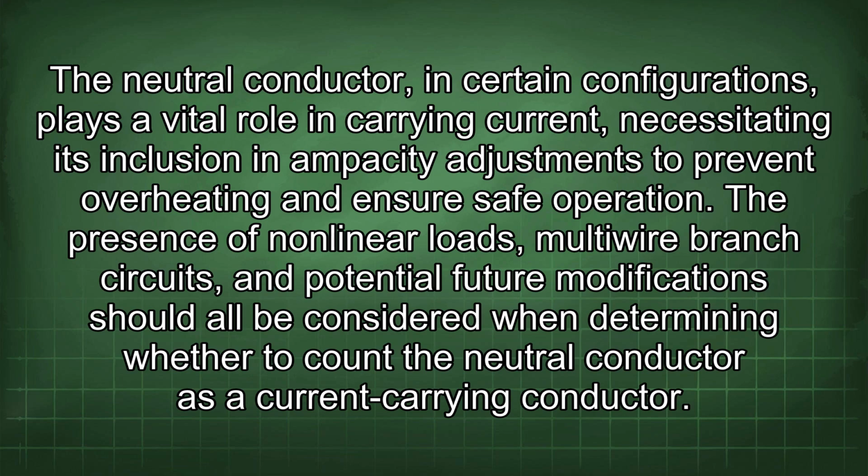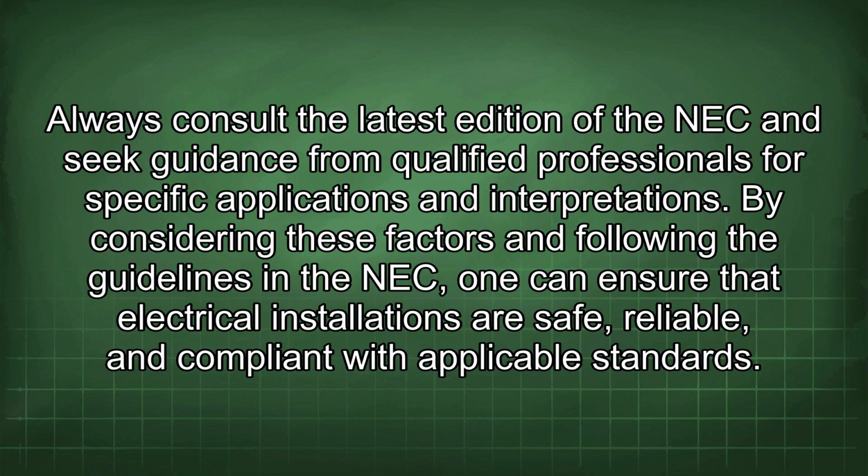The presence of nonlinear loads, multi-wire branch circuits, and potential future modifications should all be considered when determining whether to count the neutral conductor as a current carrying conductor. Always consult the latest edition of the NEC and seek guidance from qualified professionals for specific applications and interpretations. By considering these factors and following the guidelines in the NEC, one can ensure that electrical installations are safe, reliable, and compliant with applicable standards.